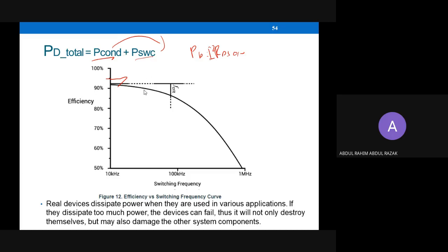And we cannot push like a signal processing system, which can operate up to maybe megahertz, gigahertz, and we now have 4G, 5G. Because once we go above, let's say 100 kilohertz, the dominance of the losses is huge. So normally we limit switching up to hundreds of kilohertz for a power processing system which processes high current. P conduction and P switching.